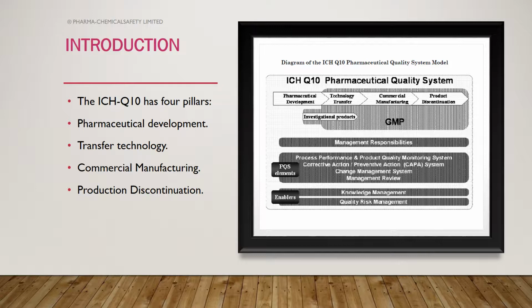One of the requirements from process safety, especially from process hazard analysis, is that once you don't have the process in your facility, the PHA can be disposed of, I mean destroyed. But you conduct PHAs in the first year and then after 5 years according to the regulation. So you need to keep the first and the second. You have to keep all the sessions registered, could be in archive files, etc. But you need to have all of those. That's a requirement. So once you discontinue the process, all those files can go to destruction. But make sure that the process is not going to come back to your facility. If it is going to come back to your facility, don't destroy anything. Keep it there, and then you're going to be fine.